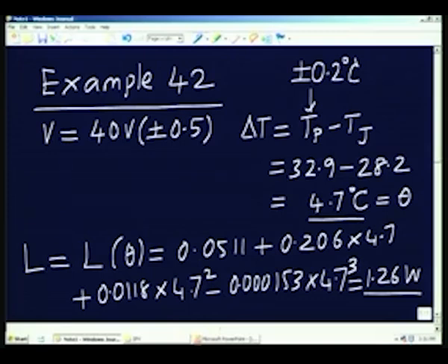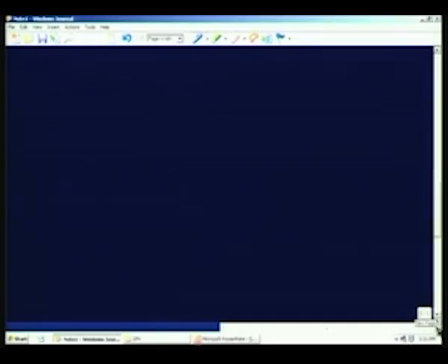Now, we will calculate the heat supplied to the heater. Under the steady state, of course, this amount of heat supplied has to flow through the specimen oil sample, or some of it is of course lost from parasitic losses through other channels, and therefore, the heat transfer through the sample is the difference between the heat supplied and the loss.